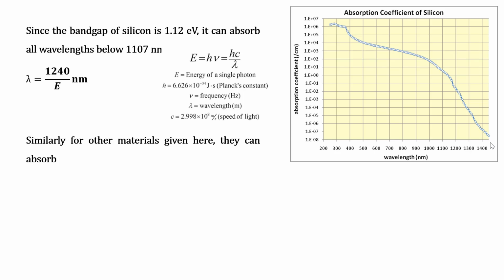That is because you have a semiconductor material, and that semiconductor material has a band gap. Any energy greater than or equal to the band gap will be absorbed by the material for creating electrons and holes. So 1.10, 1.11, 1.12, all these values will be absorbed, which means that all the wavelengths below that threshold value will be absorbed, and all wavelengths above it will be transmitted through.